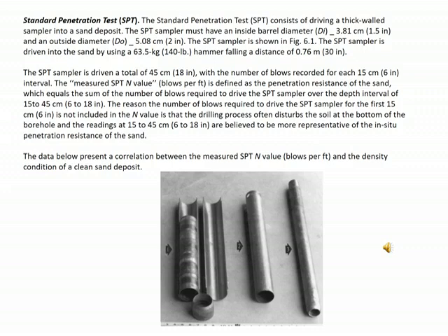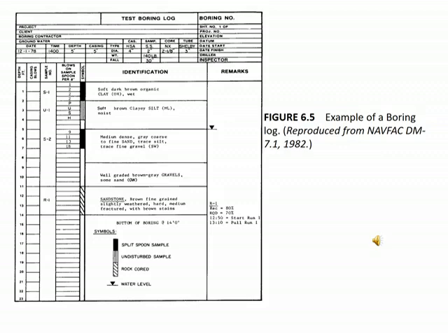On the boring log. So whenever we test a sample, we drive the sampler and then we can measure, and we take the sample. So this is a sample of a boring log. And here we see the subsurface profile. When you see the subsurface structure, there will be the water content, gray and also light gray, dark gray, and reddish, and this is medium hard. Those are the subsurface contents. Those subsurface contents need to be tested before we build on them.